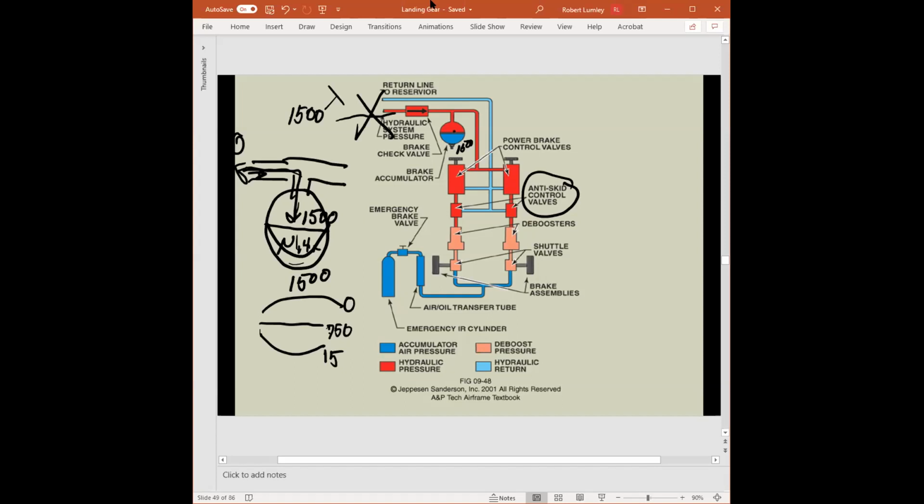Absolutely not. What you did was you pressed on the brake and then you kind of pulsated the brakes with your foot. You push down, you release, you push down and release, and that was to slow you down without allowing the wheel to skid, because a skidding tire has very little friction, okay, and won't slow you down.